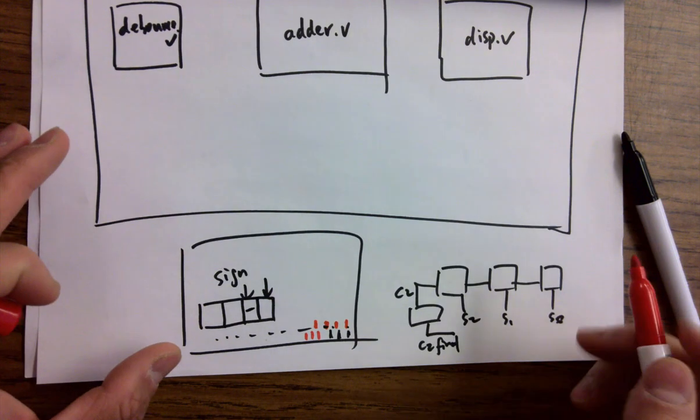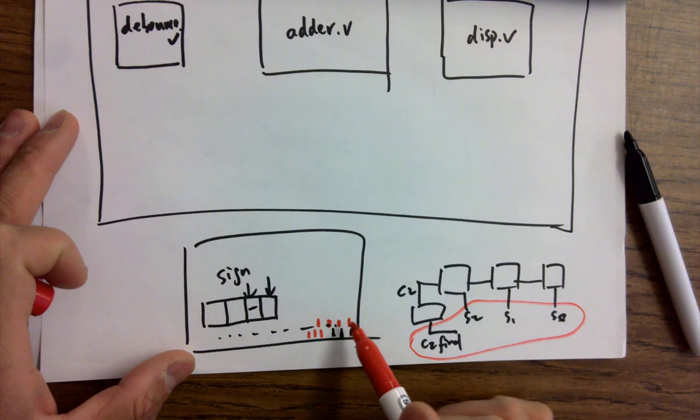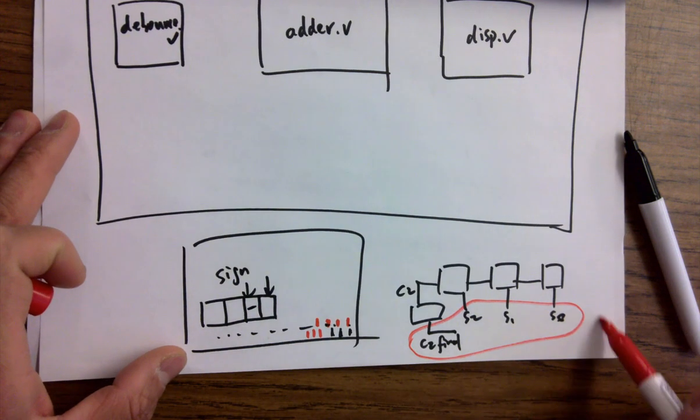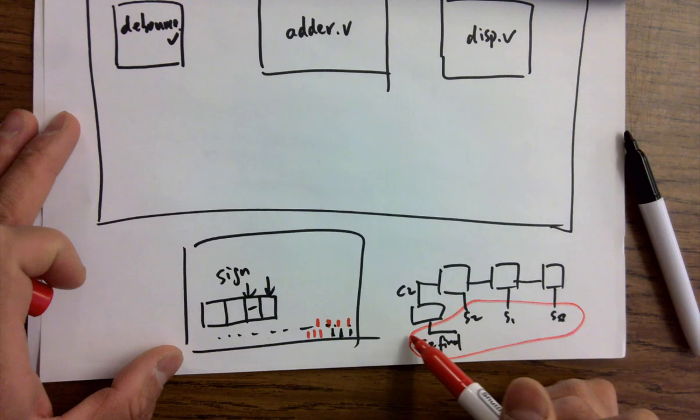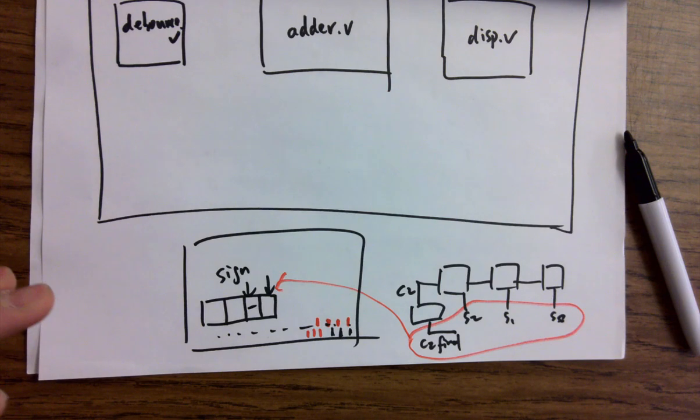So it's asking you to display this final 4-bit result at the LED, but also over here. So you can imagine if you have this 4-bit binary number available to convert it into a 7-segment display module, you only need 1 block of code. And what is that? The decoder, right? Or the case statement.